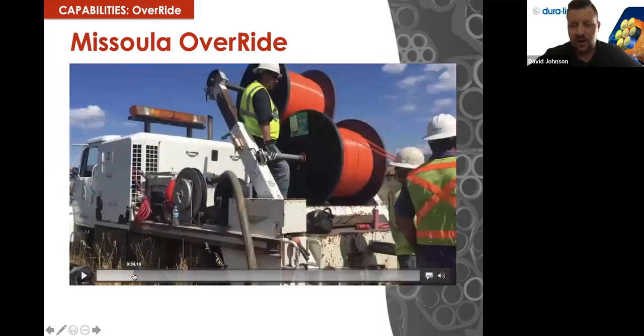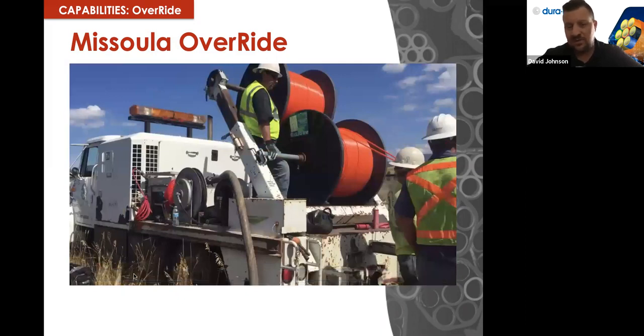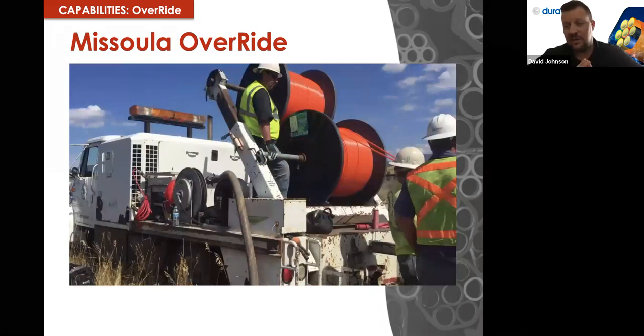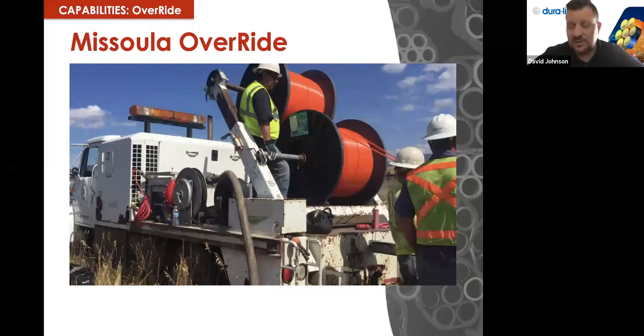They're on a reel trailer, and what's great about this is we fill this whole reel of microduct up with air pressure, because that machine, the jetting machine, the Tornado, is actually pushing down onto those ducts. So we want to have them nice and rigid, kind of like rodders into their existing infrastructure. If you've ever done rodding, these microducts essentially become rodders, and really rigid and robust.